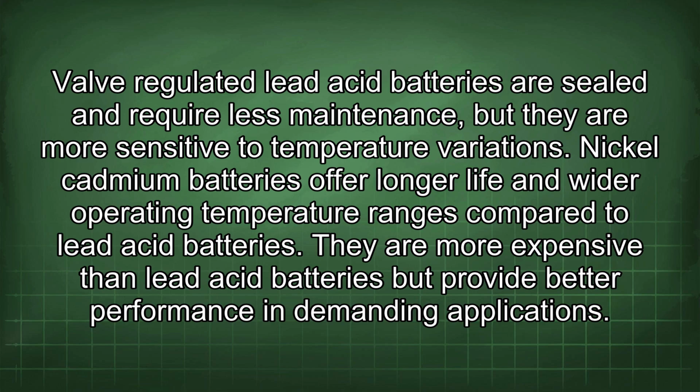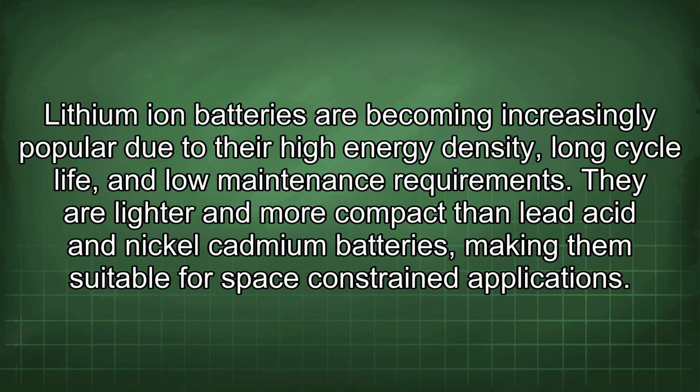Nickel-cadmium batteries offer longer life and wider operating temperature ranges compared to lead-acid batteries. They are more expensive than lead-acid batteries but provide better performance in demanding applications. Lithium-ion batteries are becoming increasingly popular due to their high energy density, long cycle life, and low maintenance requirements. They are lighter and more compact than lead-acid and nickel-cadmium batteries, making them suitable for space-constrained applications.